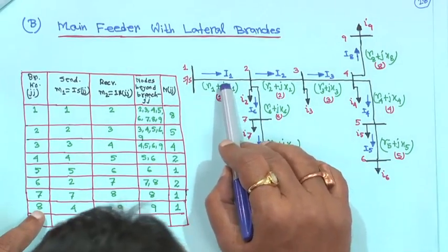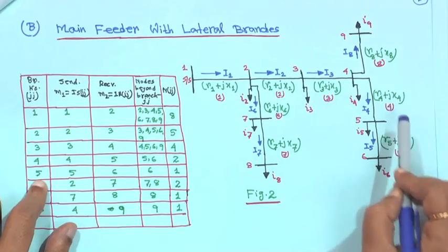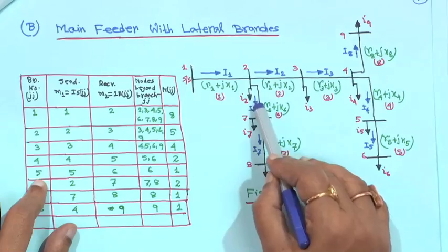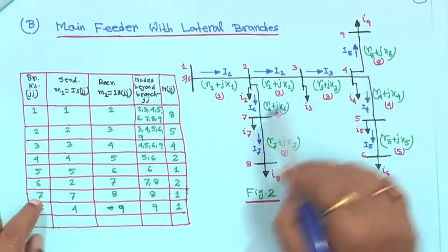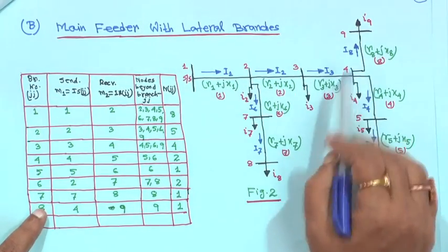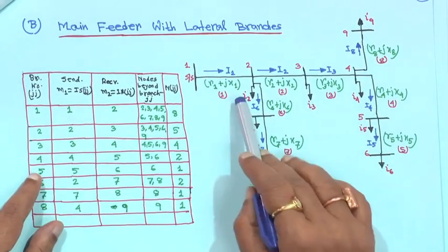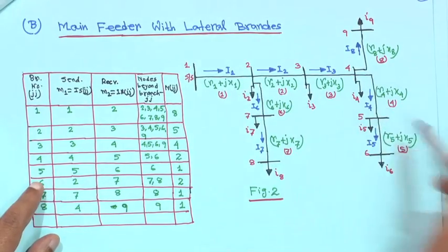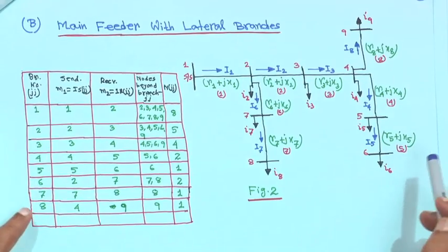So, this is branch 1; all the red marks in brackets are branch numbers 1, 2, 3, 4, 5, then this is branch 6, this is branch 7, and this is branch 8, right. Branch numbering also follows the way you mark the nodes, automatically you will proceed. But to avoid confusion, because when you generate the data in the computer we see serial numbers 1, 2, 3, 4 like this, it is better that you put your branch numbers accordingly, right.